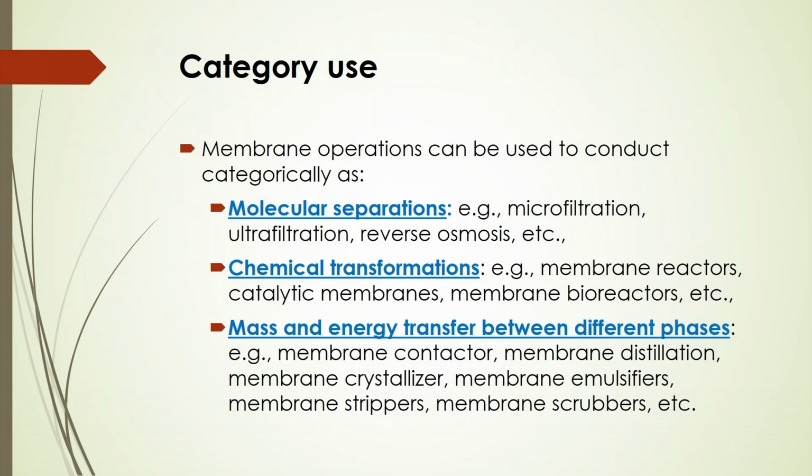Categorically, we can assess these membranes for different applications. Membrane operations cover several aspects: molecular separation, chemical transformations, and mass and energy transfer between different phases. In the case of molecular separations, you generally use microfiltration, ultrafiltration, and reverse osmosis based membranes. In the case of chemical transformations, there are membrane reactors, catalytic membranes, membrane bioreactors, etc. And also mass and energy transfer between different phases.